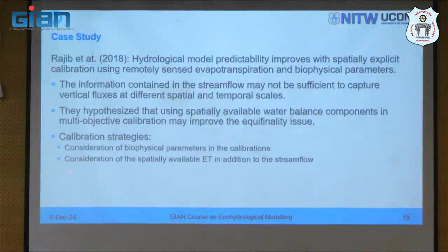At the same time, they considered the spatially available ET in addition to the streamflow, right? They used the MODIS ET data for their particular catchment, okay? So they hypothesized that although the simulations may be better, the streamflow may be more or less the same. So they were not saying that we will improve the streamflow simulations. If you see the hypothesis, they said they may improve the equifinality issue. That is, you will try to have the right results for the right reasons.